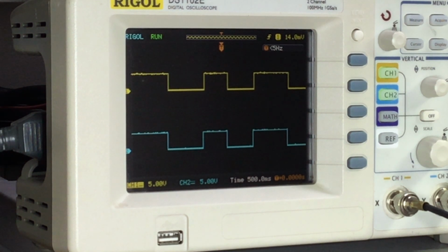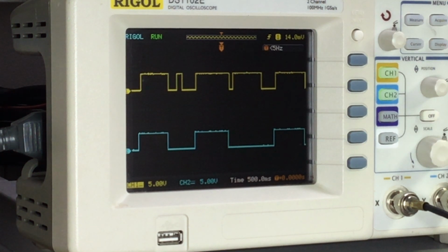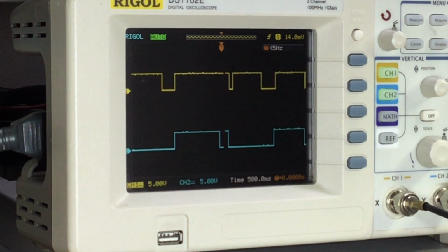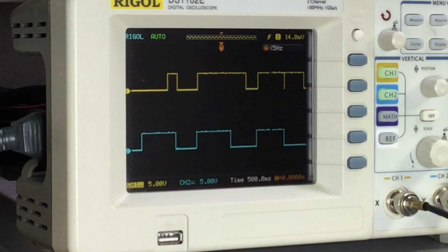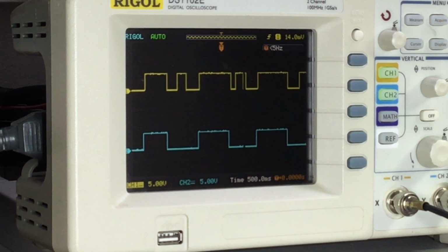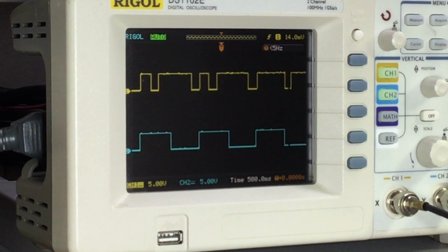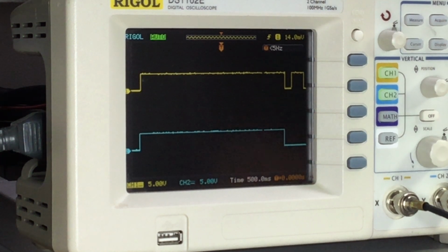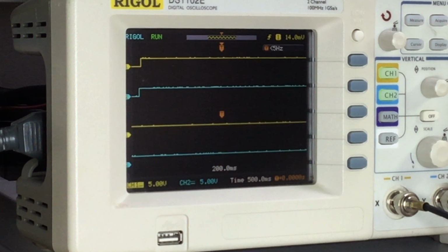So I don't know whether it's iron filings that's contaminating the sensor, or whether it's a faulty Hall effect sensor. And we've got two pulses very close together there with considerable mark space in comparison to the bottom trace. So we can see it's going all Pete Tong. It's definitely not having the best of days when you look at the top versus the bottom. So I'll just have a look at that in more detail, but let's just zoom in on that, I think.